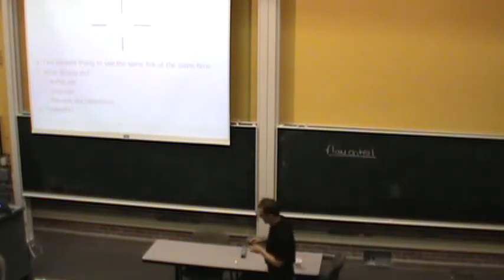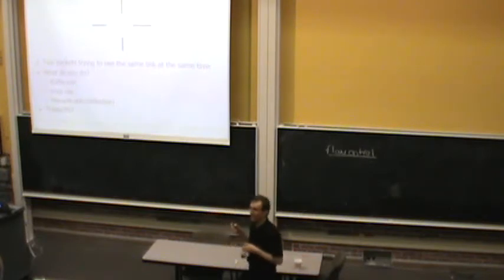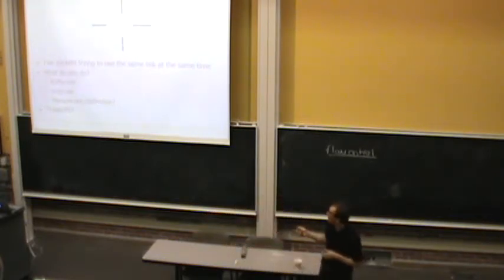And buffers consume static energy as well, right? Static and dynamic energy. You need to write to them. And even if you're not writing to a buffer, it's just leaking. Remember power consumption we talked about? So that's the disadvantage of buffering, if you will. What is the advantage of buffering compared to dropping or misrouting? Any idea?